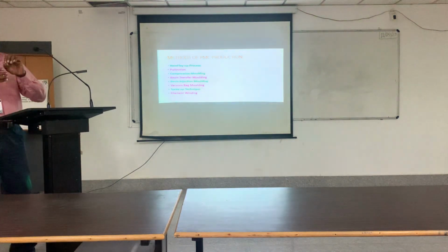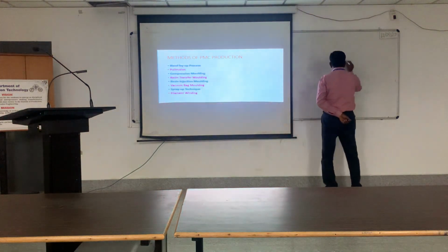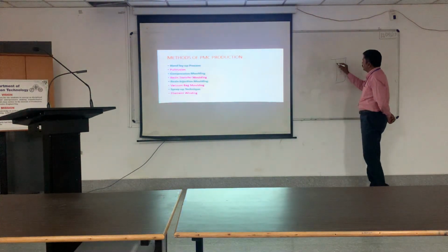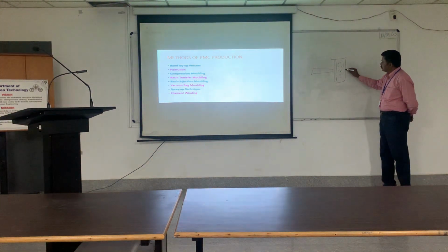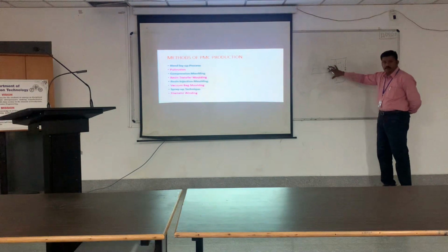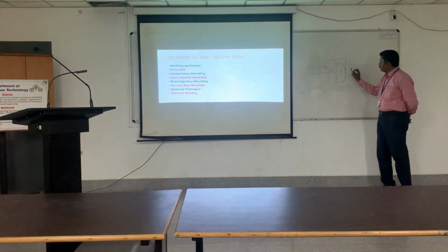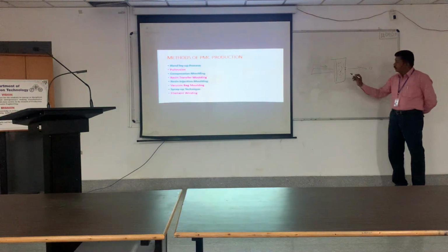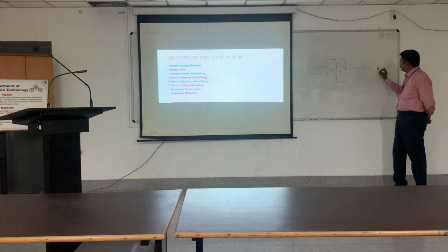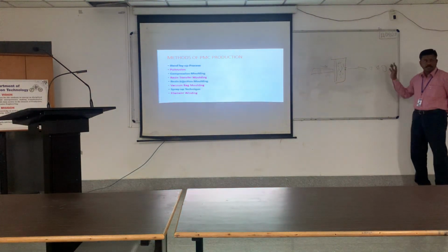So you may have a cylinder, and the material will be placed here, and you will have the piston. After placing this material, if you want a square shape, then a square hole may be here. Whatever the shape of this hole, if you give more pressure, the material will be squeezed and extruded. If you have a square hole, you get a square-shaped component. If you have a hexagonal hole, you get a hexagonal or pentagonal shape, or any other shape you want, in a linear manner.